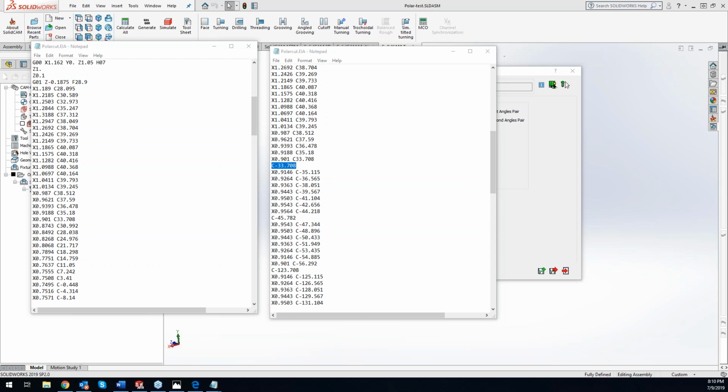Now, by doing the interpolation by points, what you're doing is you're breaking up that line segment into a bunch of little points. That way you can change that radius value and kind of fake that straight line as it's going. So instead of going from one corner to the next as a point to point, like we normally would if there was a straight line in between it.